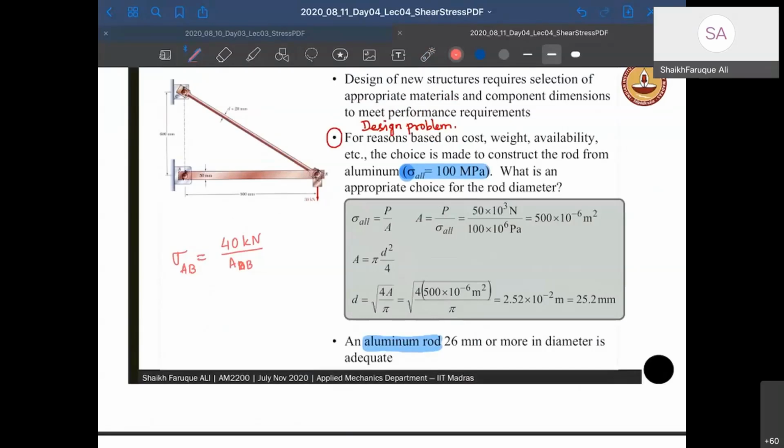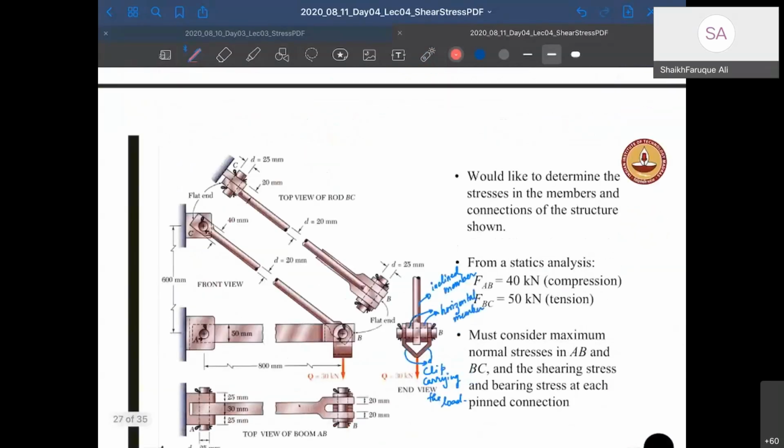See, most of the, I'll tell you this, please note it down. Most of the metal structures will have similar maximum allowable stress in compression and tension. Most of the metal materials. So if it is 165 in tensile, it will be 165 allowable stress in compression also. But non-metallic materials like wood or concrete will have different allowable values in compression and tension. So in that case, you have to look properly at what the tension is and what the compression is.